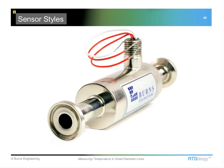Another sensor that may work well for the 5,000 psi could be something like this, where it's replacing a section of the piping, and we just have to put the correct style connections on it to handle that pressure. Again, a non-intrusive sensor like this is a real good way to get into an even smaller line, like a 1/4-inch diameter on up. And it's a surface measurement, but you're going to get fairly close, maybe within a few tenths of a degree of the actual temperature of the fluid.